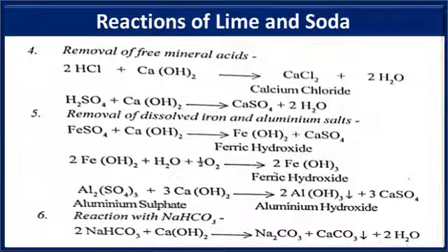Whenever sodium bicarbonate is present, always remember that it consumes the lime but it generates the soda. And in which ratio? We can see here 2 moles of sodium bicarbonate consume 1 mole of lime. That means 1 mole of sodium bicarbonate consumes half mole of lime, which produces half mole of soda.